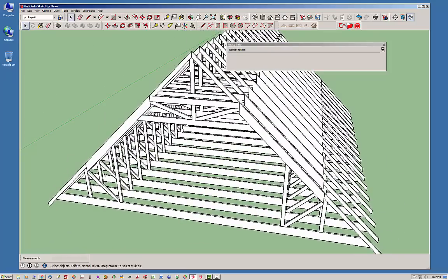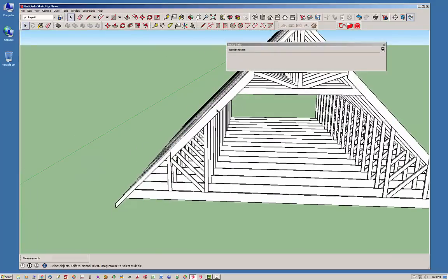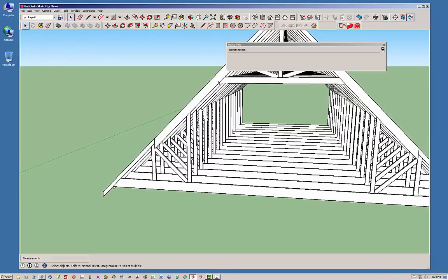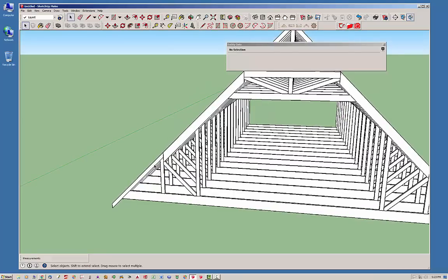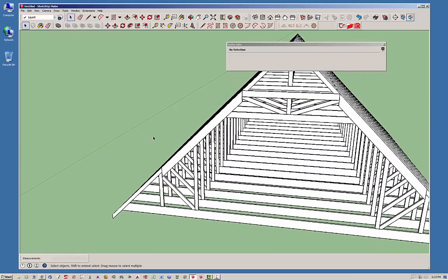But anyways, what ends up happening a lot of times, as you'll notice, is that this top chord member is substantially thicker than this overhanging portion. You specify this depth because you want to get insulation through this diagonal region of the ceiling, and that depth you actually specify. This is typically 2x4 or 2x6 here, and you don't care that this overhanging portion is 2x8 or 2x10 in depth. So that's why this configuration is very typical for this type of truss, where you have a double split top chord, as I call it.